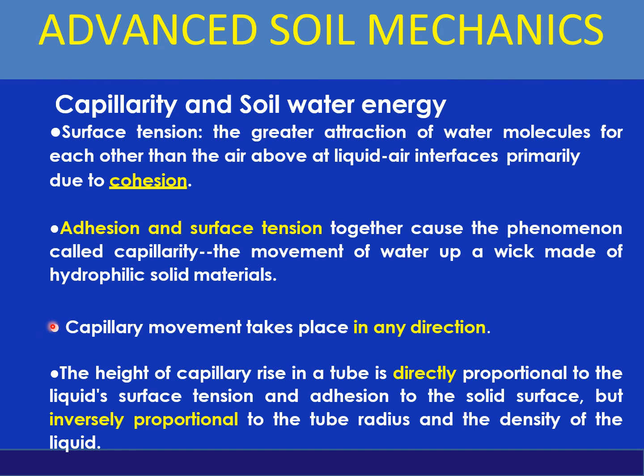Capillary movement takes place in any direction. The height of capillary rise in a tube is directly proportional to the liquid surface tension and adhesion to the solid surface, but inversely proportional to the tube radius and the density of the liquid.